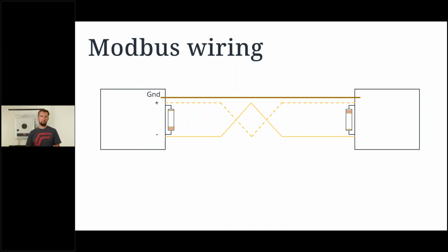You'll often hear of Modbus and echoes or reflections. That is usually when there is no termination resistance and those stray signals come back and are misinterpreted as data, or they end up corrupting another signal. So a very important part here, the termination resistance at the end of our serial connection.